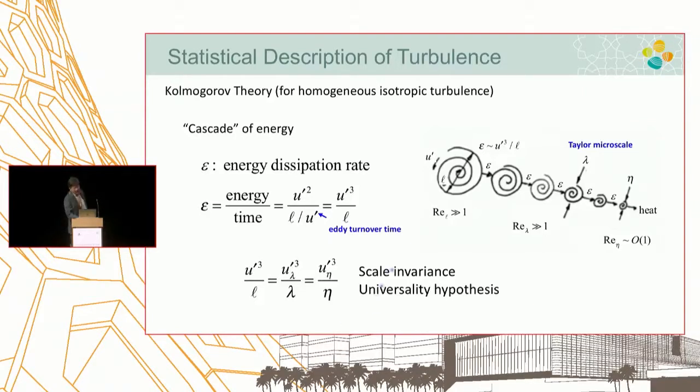So basically what is believed is that turbulence is characterized by a whole bunch of eddies. Eddies are just circular fluid motion. And there are scales of eddies depending on the diameter and spinning velocity. You can characterize a turbulence in terms of a velocity scale, which is called U prime, and L is a length scale. Diameter, circumference, it doesn't really matter. That's only a factor of 3. So for all scaling purposes, it's on the ballpark.